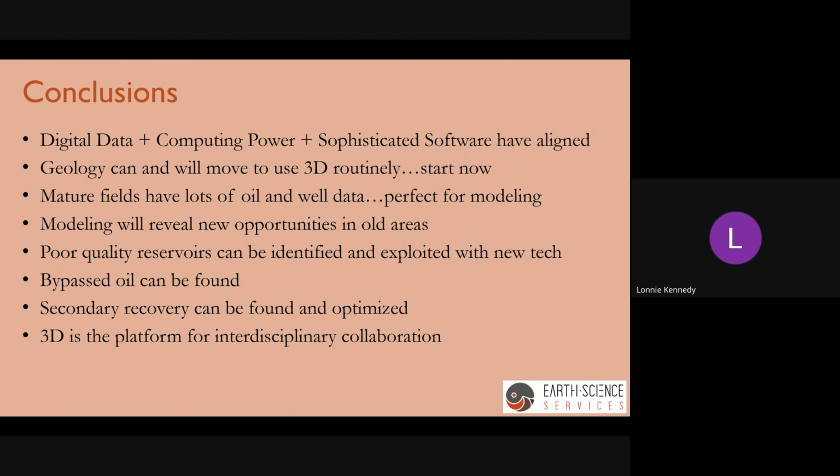Yes, sir. I was curious how you use a gridding algorithm to do this operation, because there isn't just one, there's a variety of different gridding methods, and it's going to affect the output. You're going to get different numbers from different grids. So what decision process do you go through up front to say, we're going to use inverse distance weighting, or we're going to use spline, or we're going to use triangle? How do you make that determination?